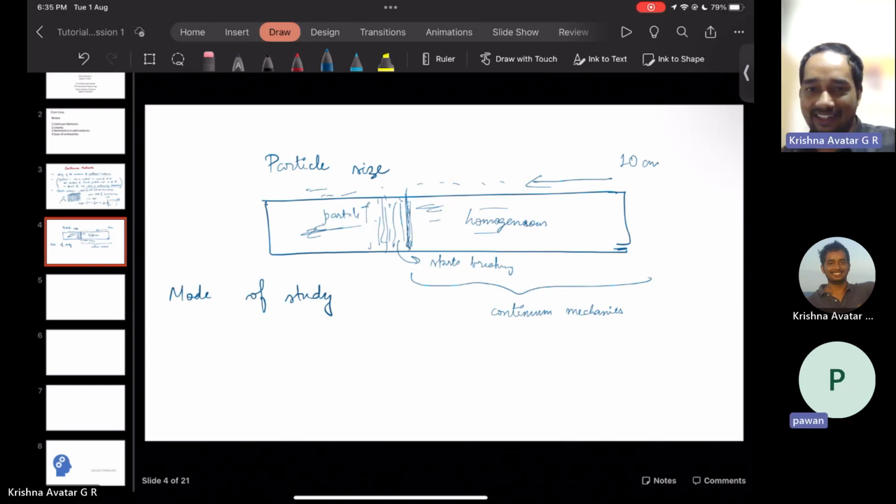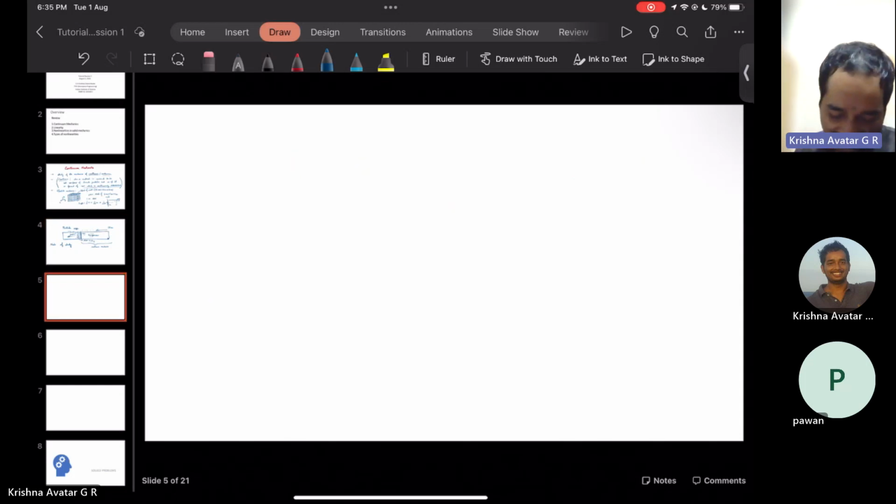There, we cannot use the very traditional methods such as Newton-Raphson approaches. So we use a technique called arc length approaches, wherein we can model very non-intuitive deformation patterns. Let me recall the problem. So the problem goes something like this.